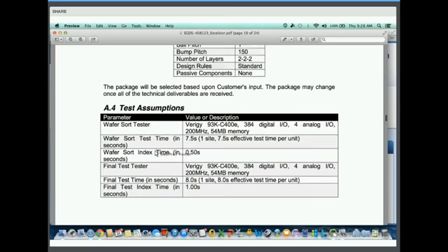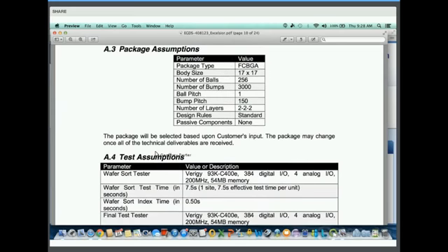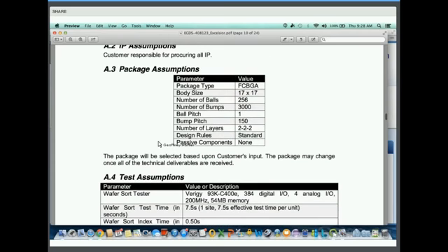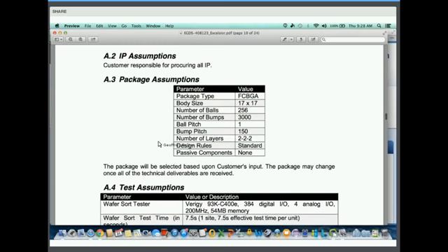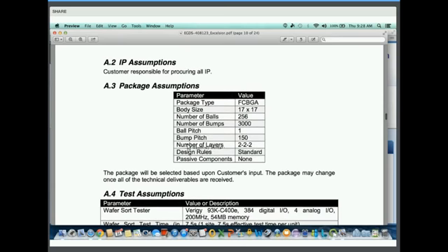Yeah, I think working together on DFT, we could maybe reduce the number of pins required and do dual site test. Okay. And is it possible maybe on the package to go down a level and have a 121 instead of a 222? Yeah, 121 is a cheaper platform for sure, and maybe we don't need the extra power planes in there.